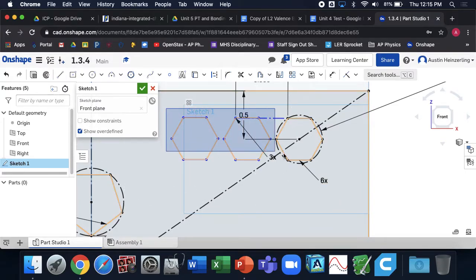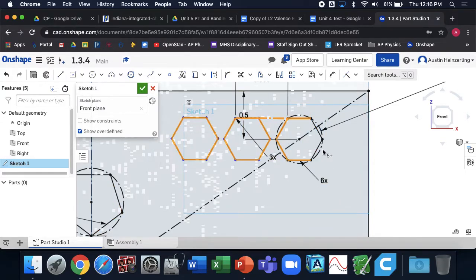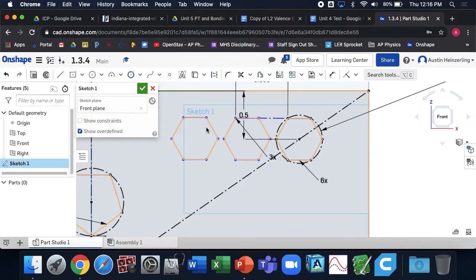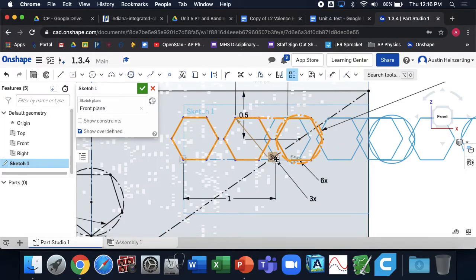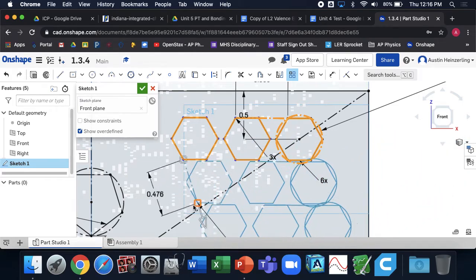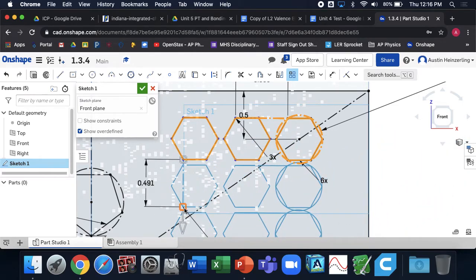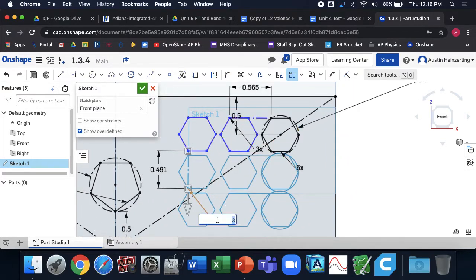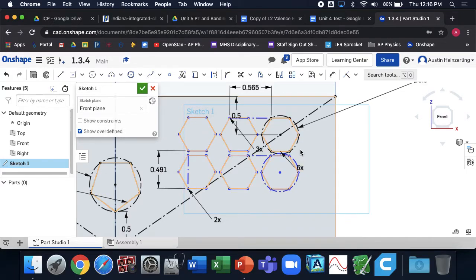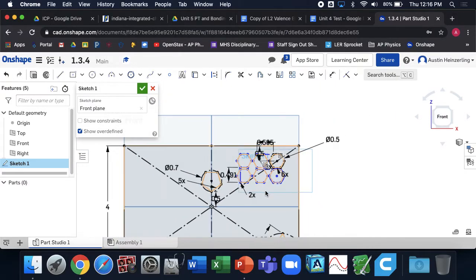Well, then I'm going to select all those, and I'm going to pattern the other way. Right? I want this to go down. I did it. You see my 3 times? I want to double click, so I say, I don't want 3 of them, I want just 2. And see this green check mark? I can confirm, yep, that's what I want. That'll make my pattern.